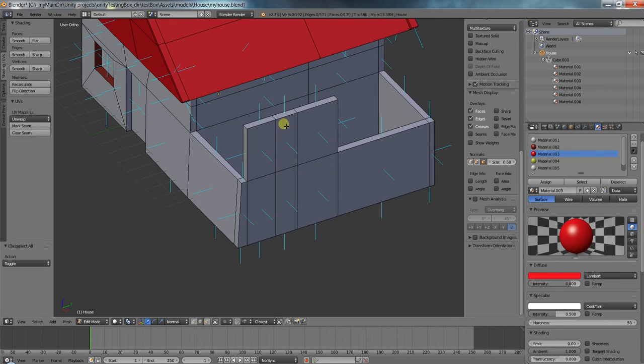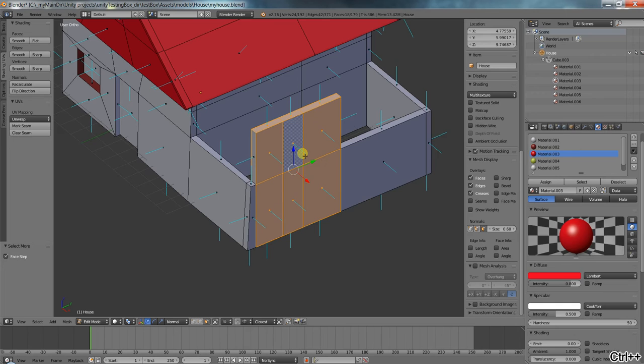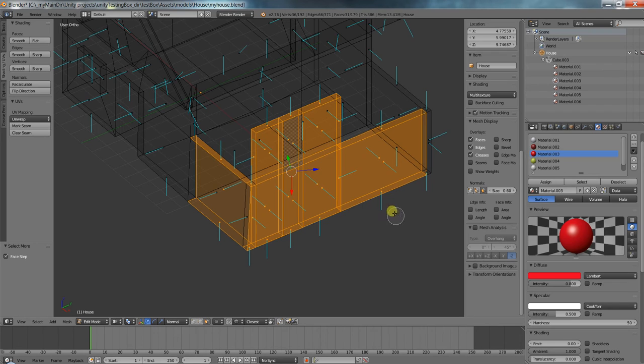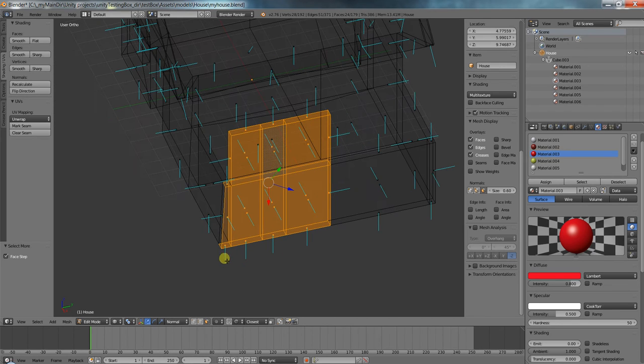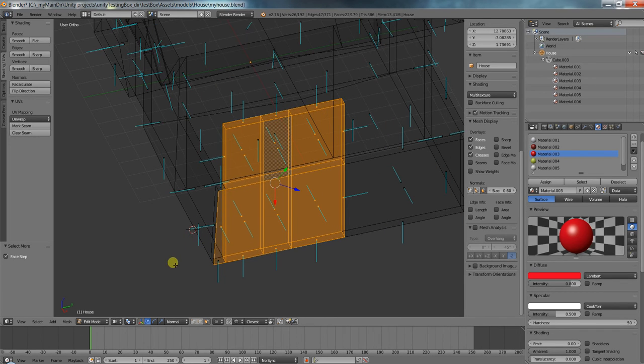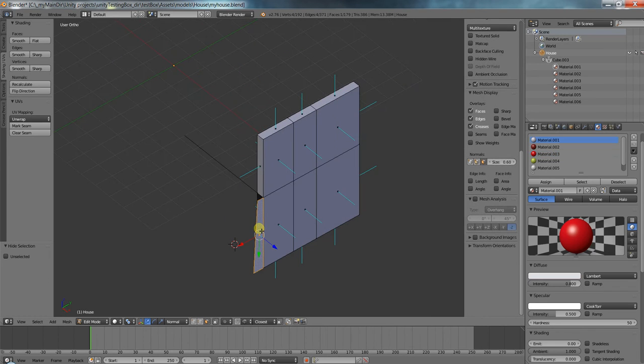See these two lines. First of all, let's get rid of everything else but this wall. So Alt select this, Control plus Z to look through, and C to select or deselect. It toggles select or deselect. Okay, I don't even need these. Control I to select everything else. Hide. Z to make everything visible. Hide this. Hide this edge.